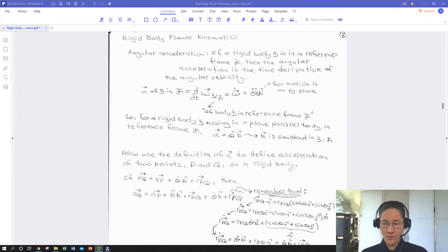And because that rigid body is rotating in plane, we're only talking about planar motion, all of our angular position, our angular velocity, and our angular acceleration are all going to have vector directions normal to the plane of motion. So we're saying that we're moving in the xy plane. So our rotational velocities and accelerations are all going to have direction in the k hat. So out of plane, planar normal. Now it could be positive or negative k hat, but it's definitely going to be in the k direction for motion in xy.